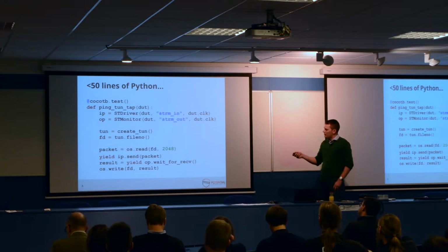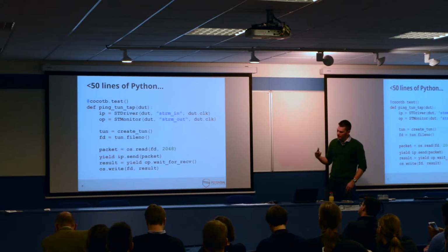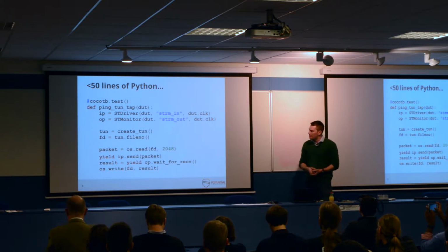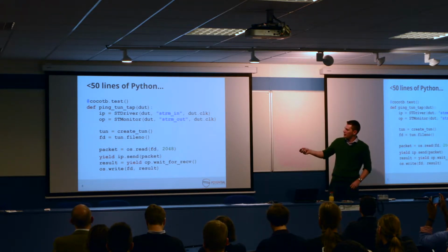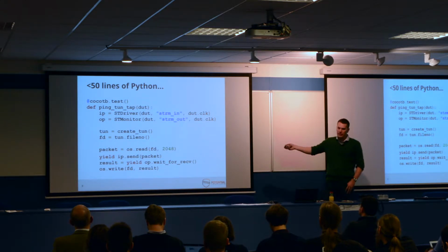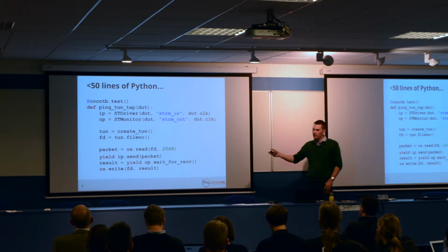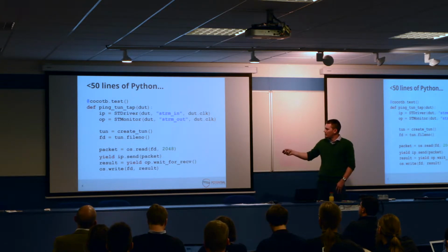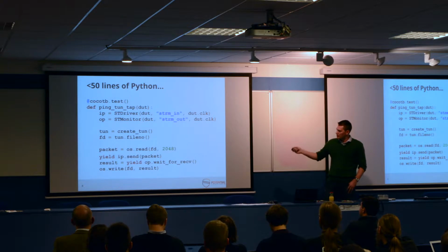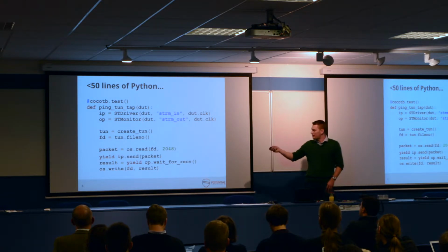We then hook up our drivers and our monitors to the design. And again, this is where Python really stands out, because we have reflection and introspection capabilities. Hooking stuff together is really easy. We can discover all the signals with this name, or we can query the design dynamically. So we're just going to look for all the signals that match this name associated with this clock, and that's our driver, same with the monitor.